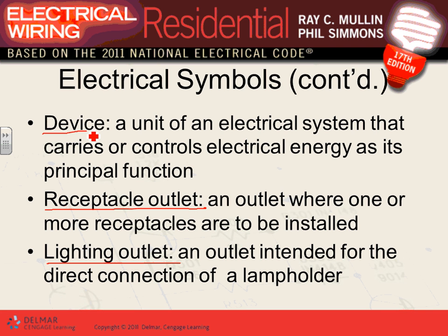Now, Derek tells me, well, I have a switch that has a little pilot light on it, Chad. Well, that's meant for indication only. It will consume a little bit of power, but 99.99% of the function of a switch or a device is to control the flow of power, not to consume power. Cool? That's the difference between an outlet, a receptacle or lighting outlet, and a device. Any comments, guys? Any questions about these?